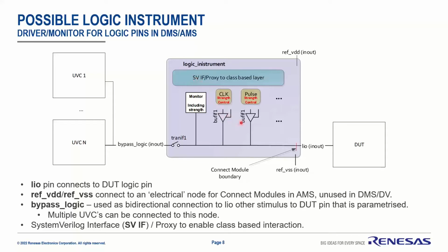And in there, I've got some very basic drivers like driving a clock, driving a pulse with strength control, driving ones and zeros. I've got some monitors in there so that we can get the value of this net, get the strength. I give it a VDD and VSS, and I make sure that if a connect module is needed for AMS, say that the dot pin here is electrical, it would insert the connect module on this boundary